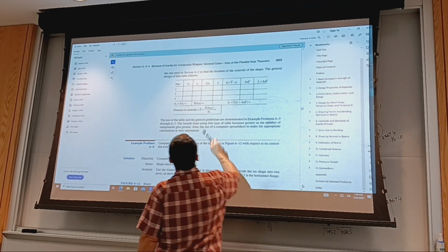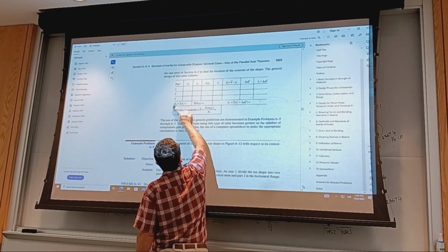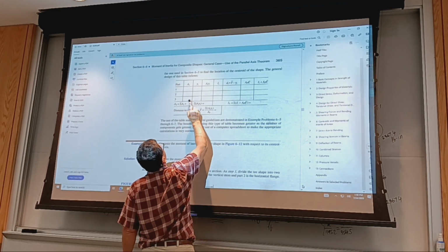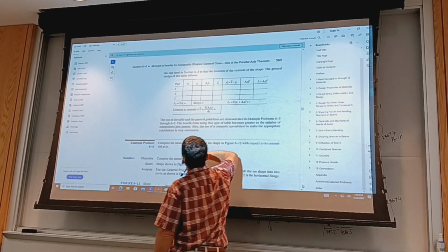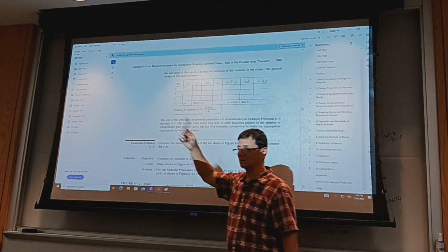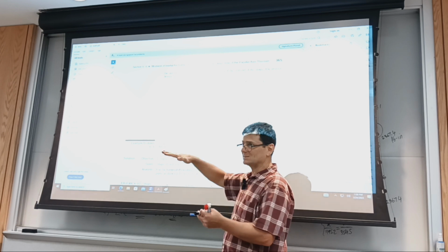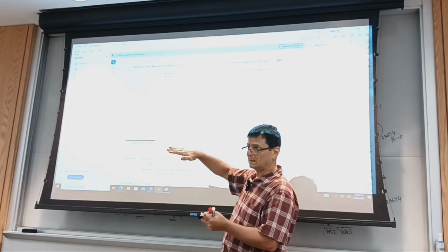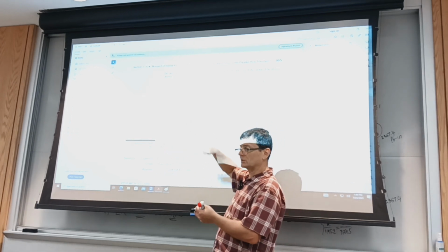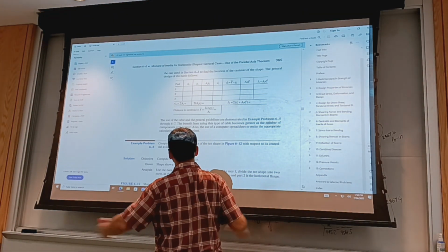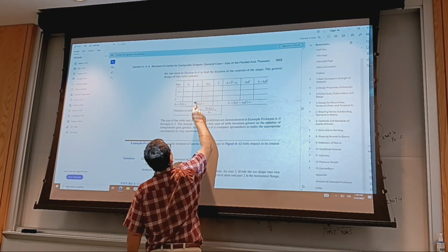And we have, so the first up to here, we calculate the centroid. So part 1, 2, and 3, its area, the distance from the axis to the centroid, it could be a signed number, could be positive or negative, if the reference axis is somewhere above or intersects the part. Usually we take it at the bottom level for all these values to be positive.